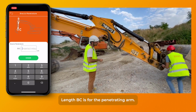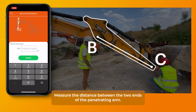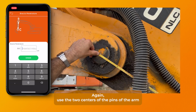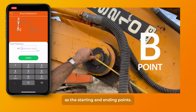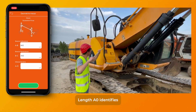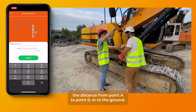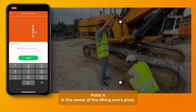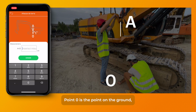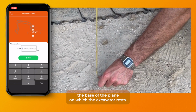Length BC is for the penetrating arm. Measure the distance between the two ends of the penetrating arm. Again, use the two centers of the ends of the arm as the starting and ending points. Length A0 identifies the distance from point A to point 0, or to the ground. Point A is the center of the lifting arm's pivot. Point 0 is the point on the ground, the base of the plane on which the excavator rests.